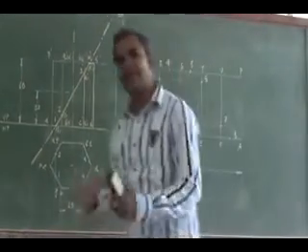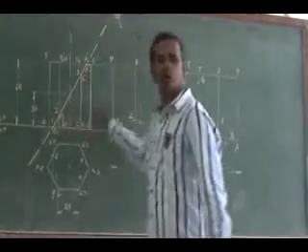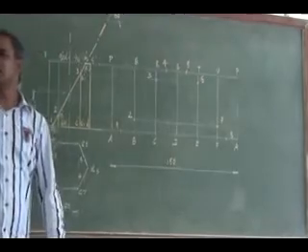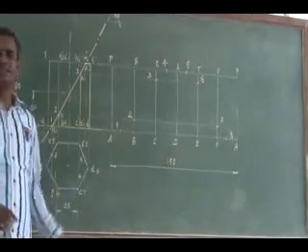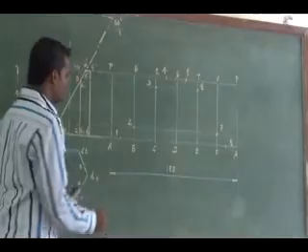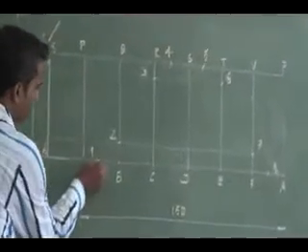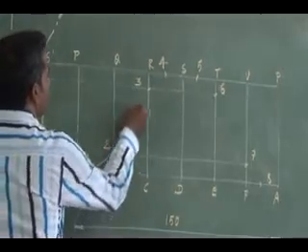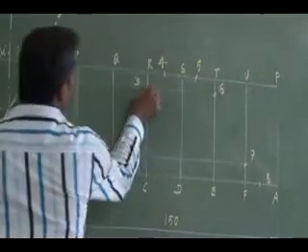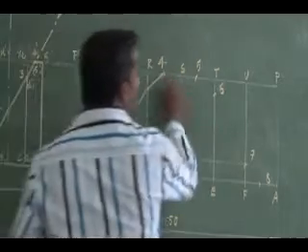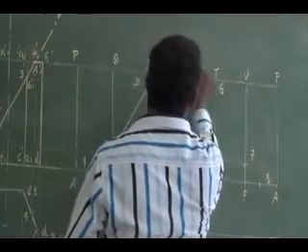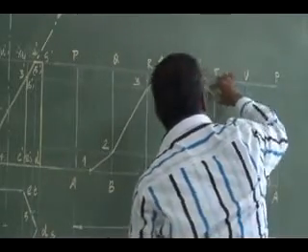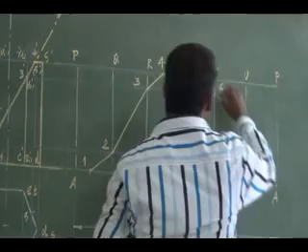Right. Then, which is my retained portion here? The bottom portion that you have drawn. So you just connect these cutting points in a sequence with a straight line. With a straight line, I have to join these cutting points to show the cutting location. 1 to 2, connect it with a straight line. 2 to 3, a straight line. 3 to 4, then 4 to 5 with a straight line. Then 5 to 6, the straight line. Then 6 to 7, the straight line.